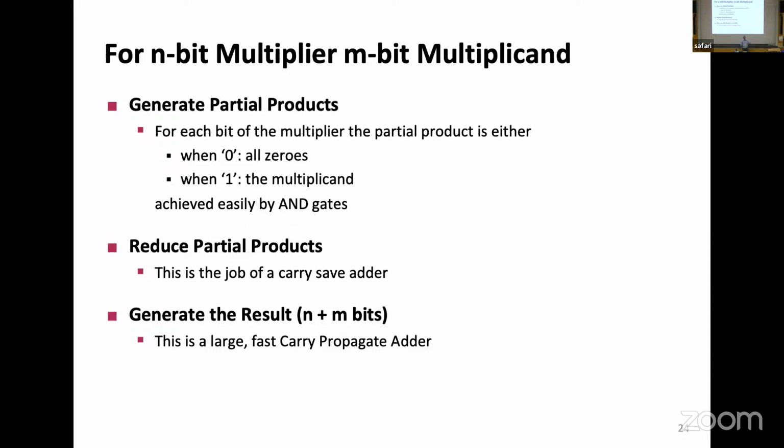So 8-bit times 8-bit will give us 16 bits. Okay? And remember what the problem was? The larger the adder, the more we were suffering through the curse of the carry. And guess what? In a multiplier, we end up with a particularly large carry propagation chain. So making the adder faster would pay off that much more here.